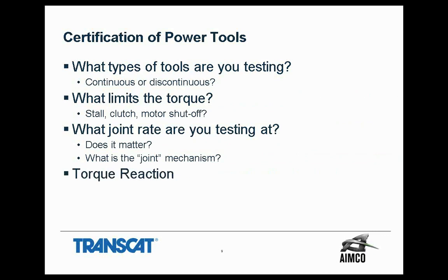If you are using hydraulic wrenches or large torque multipliers, you're going to have a lot of torque reaction. To deal with torque reaction, you must stay perpendicular, square, to be safe and to be accurate. The closer you are to the output spindle, the more force you have. If you have a 5,000 foot-pound tool and your reaction post is 6 inches away from your spindle, you have 10,000 pounds of load at full torque. That's a lot of force, and it has to be perpendicular and square, and your structure has to be able to withstand that. It's extremely important.